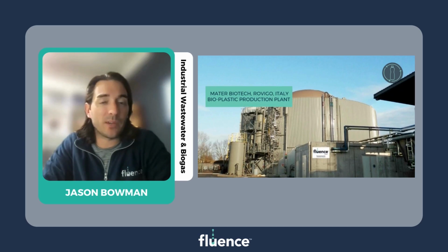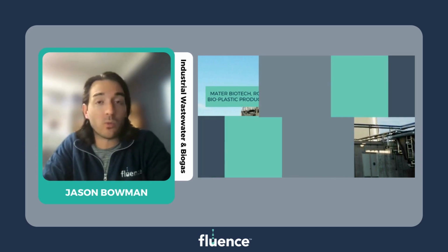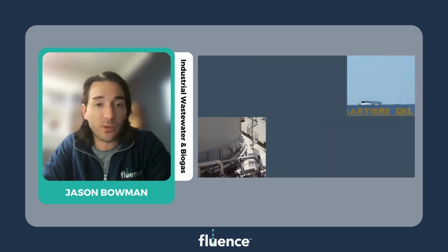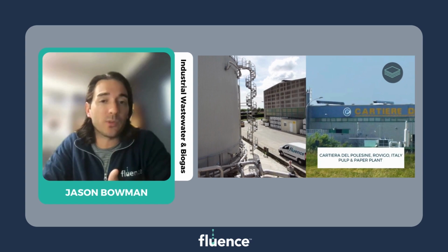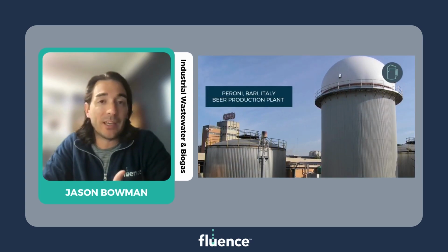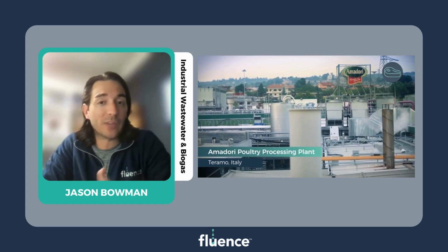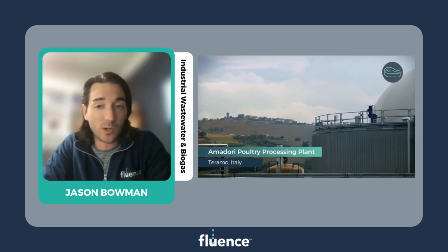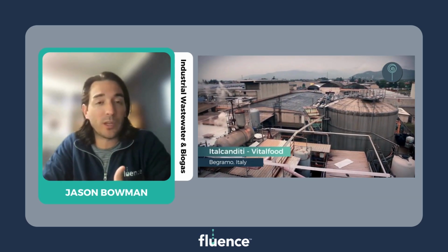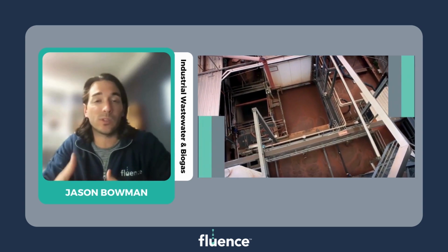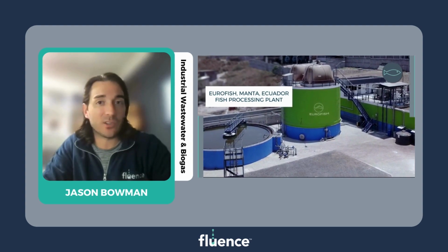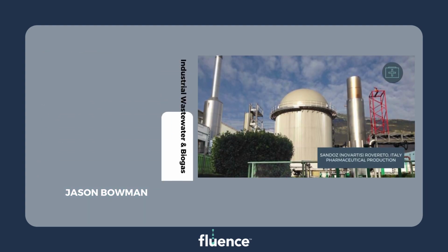These digesters can provide a mechanism to treat wastewater or reduce their sludge volumes or change the impact to their carbon footprint. So this approach often affords a more holistic waste treatment or wastewater treatment mechanism and can reduce the burden to downstream areas or receiving bodies of water. Obviously, at the same time, it's producing biogas, but what I want to point out is these systems have a more holistic wastewater reduction footprint and not necessarily need to be a biogas powerhouse.